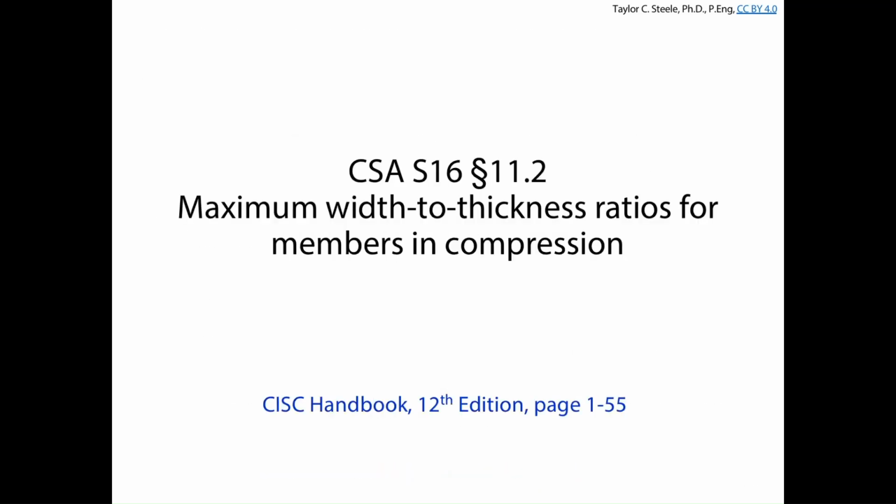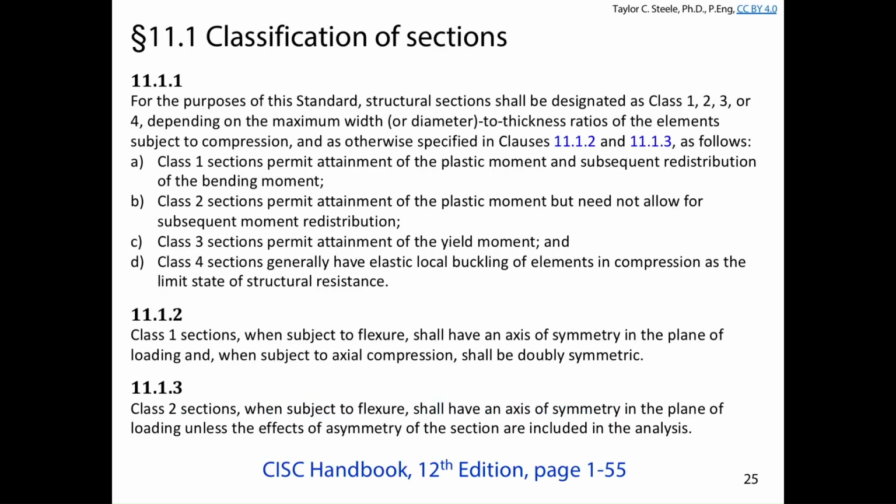Okay, so this all depends on, as you might have guessed, width to thickness ratios. Right? So we looked at width to thickness ratios for compression members. B over T had to be less than or equal to 200 over the square root of Fy for the flange, and less than or equal to 670 over the square root of Fy for the web. And that was for members under axial compression only, and we used Table 1 to find the upper limits on those.